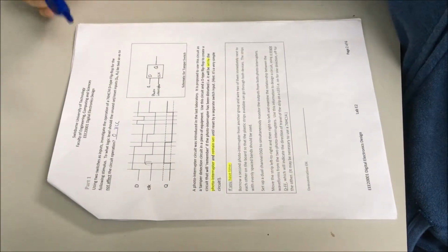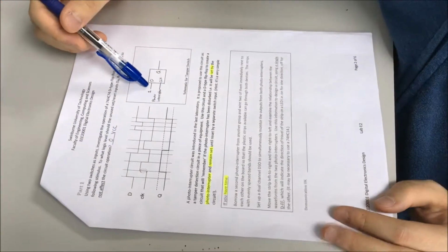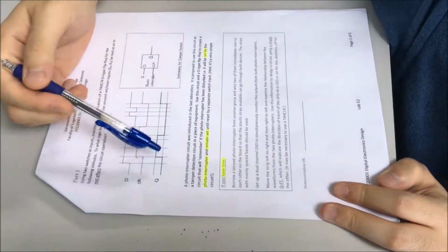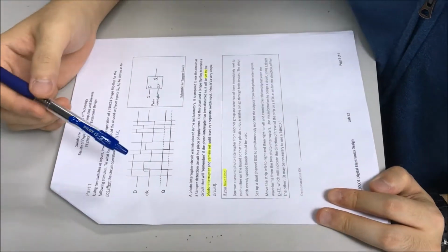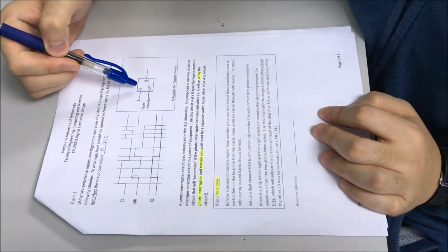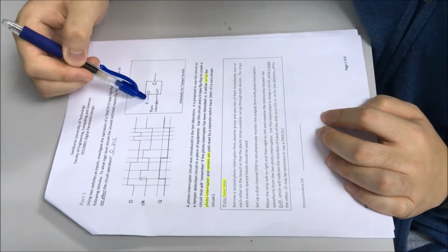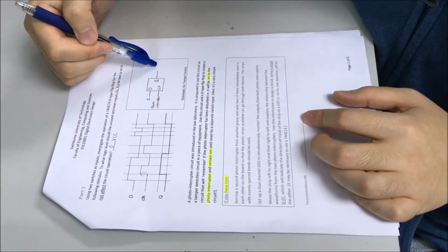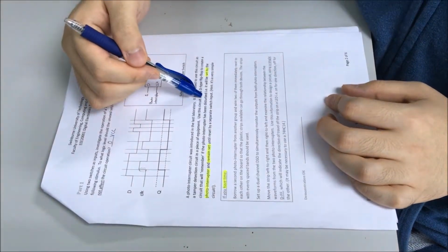Okay, so now I will explain the part for part 1 and the tamper switch. For the tamper switch, I'm assuming that the photo interrupter circuit will give a value of 1, which is high, once the circuit has been triggered. So I will wire the photo interrupter to clock, and I will wire D to VCC, which is high input. Once the photo interrupter has been triggered, it will cause Q to go to high, and this state will remain, letting us know that the photo interrupter has in fact been disturbed.